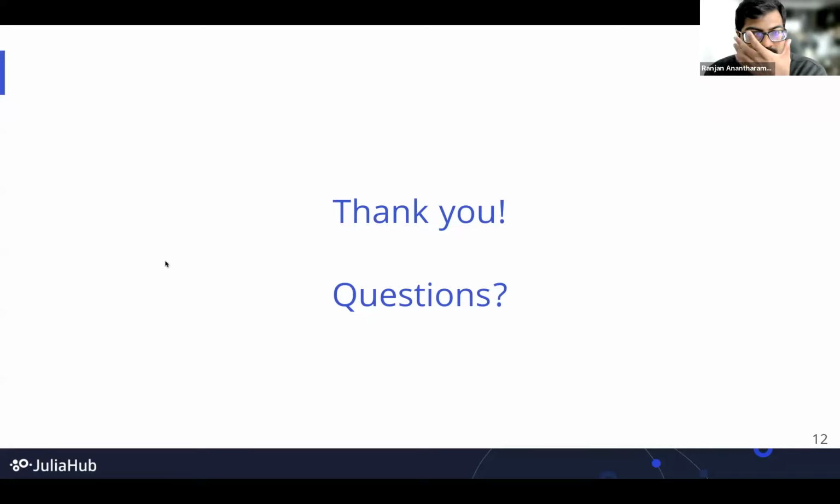I have a question on when you simulate a cycle, how many time steps are chosen for a particular cycle? Could you answer that? Yeah, so in JuliaSim and JuliaSim Batteries, we use advanced ODE, or ordinary differential equation, and differential algebraic equation solvers, which use adaptive time steps. So we don't pick the time step ourselves, the modelers. These are just determined via simulation, and we're solving very stiff problems here, so it can adaptively change the time step to deal with that stiffness.